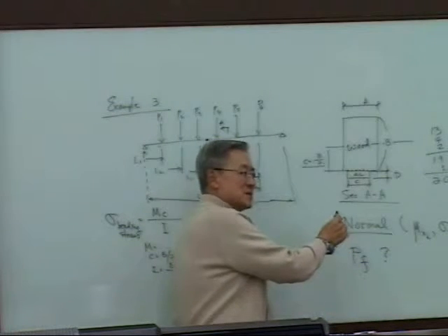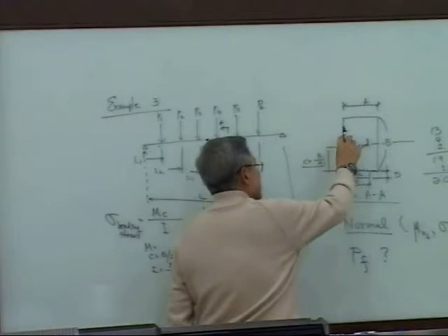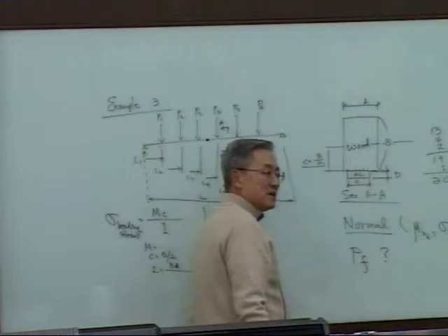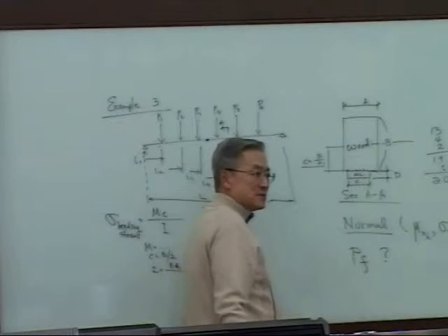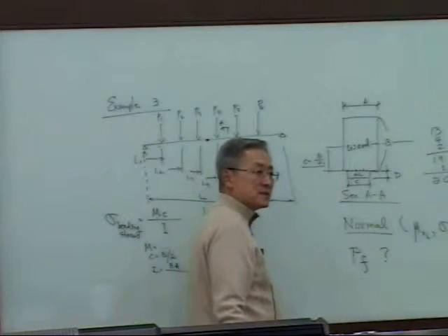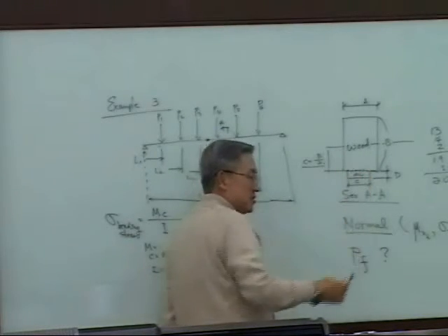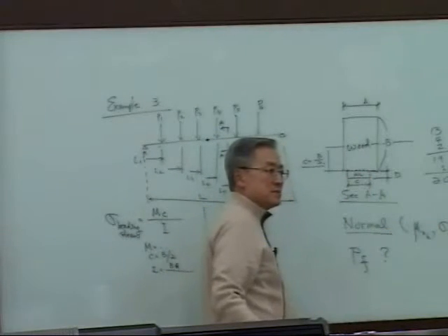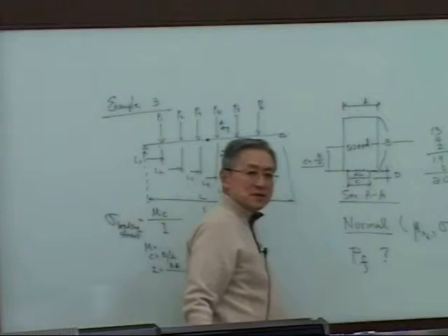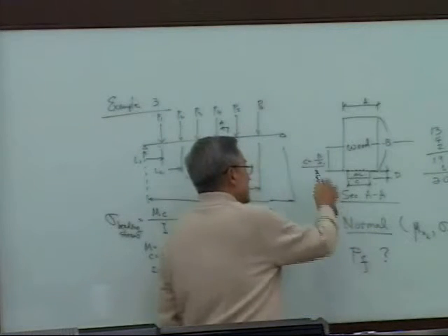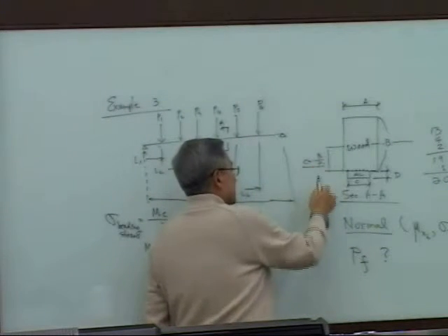Aluminum is there also, right? This half is only for wood. And aluminum, you have to add the aluminum. About the neutral axis, you have to compute the neutral axis also, because this is an additional plate at the bottom to better resist tensile stresses. So you have to modify this, right?